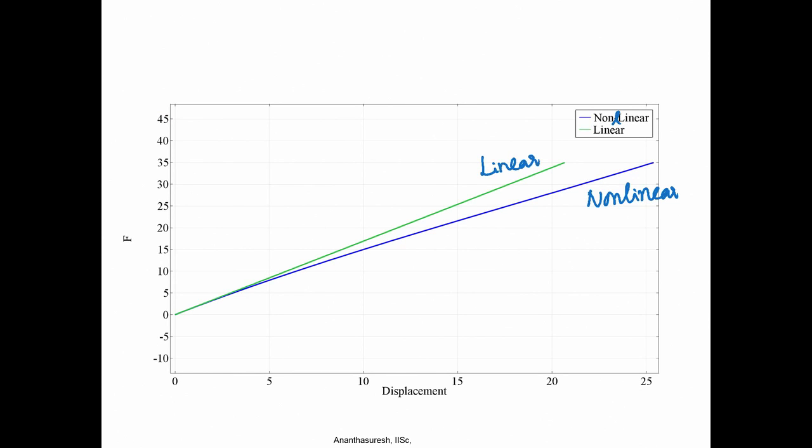In general, for most compliant mechanisms, for the same force, if you were to look at the slope, it looks stiff for linear and not so stiff for nonlinear. This means that in the nonlinear case the slope is reduced, meaning it is more flexible, but in general that is not true. The nonlinear analysis will give you stiffer behavior compared to linear.